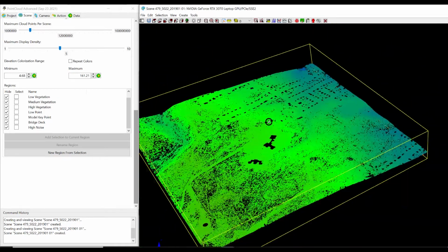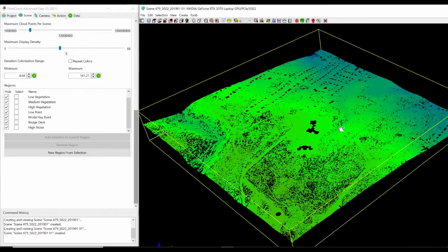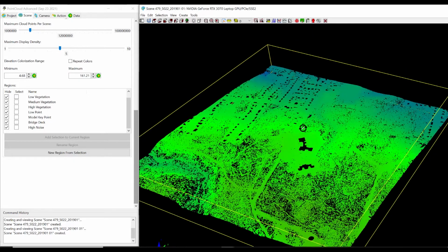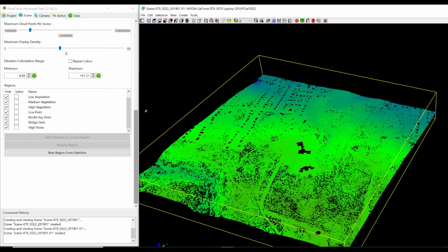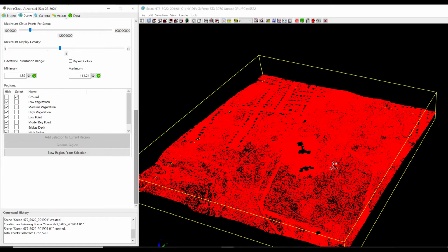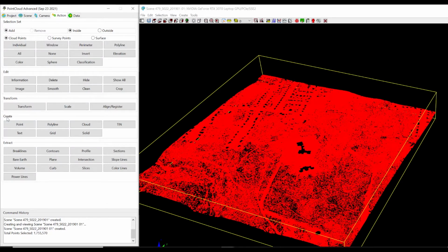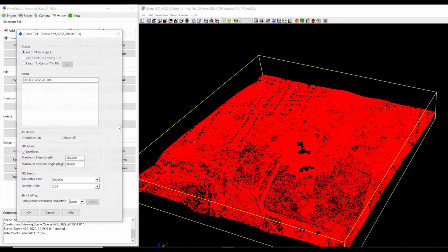That's incredible. Now, we do have, of course, bare earth functionality that we can process with, but in this case, we don't have to. So we come in here. Now I'm just going to basically say, okay, select the ground. And again, I could take part of this if I wanted to or whatever. And then I just come over here to actions and I say create a tin.